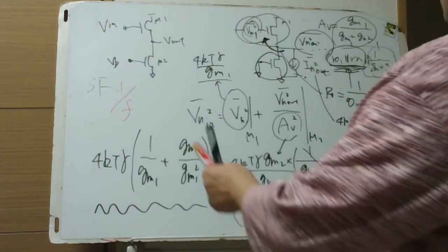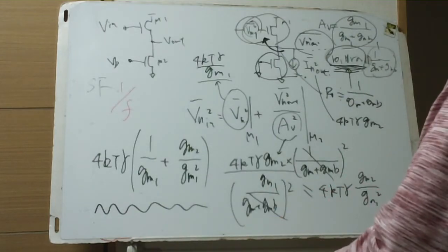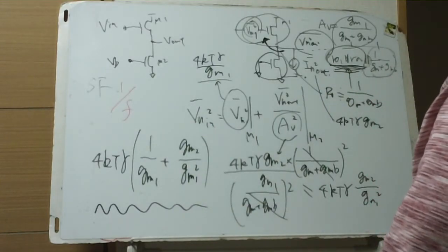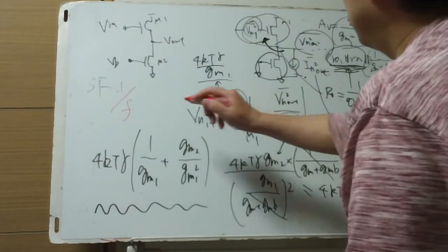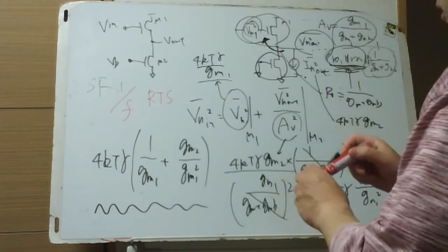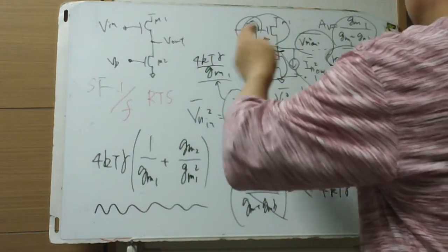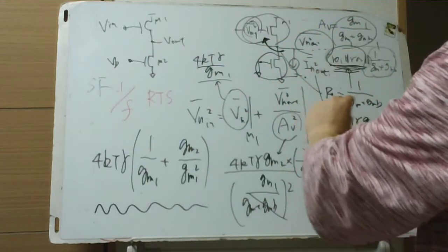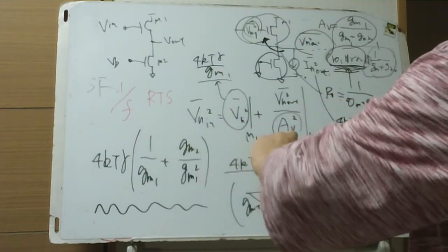Flicker noise is modeled to appear as gate voltage noise, and seems to be caused by random telegraph signal noise, caused by defects in the very thin silicon dioxide oxide layer.